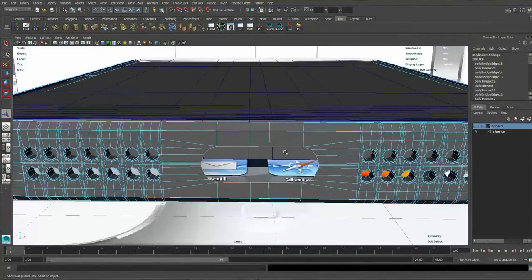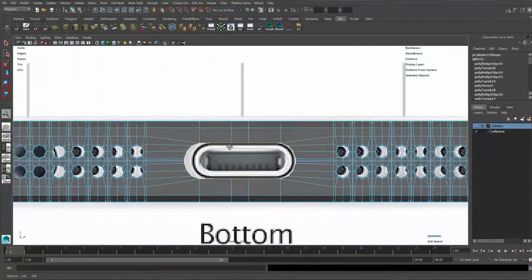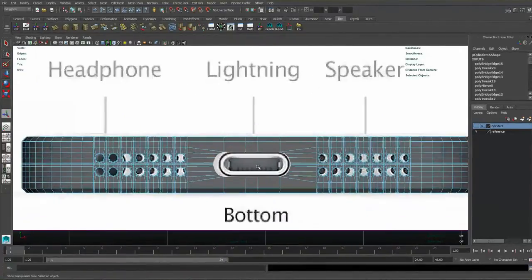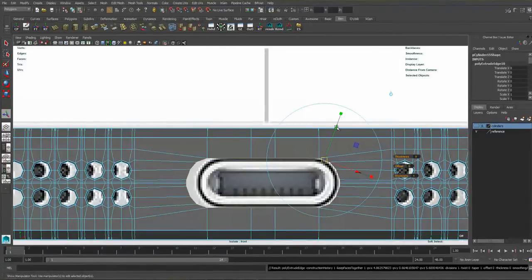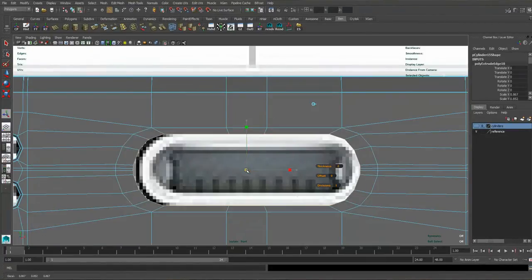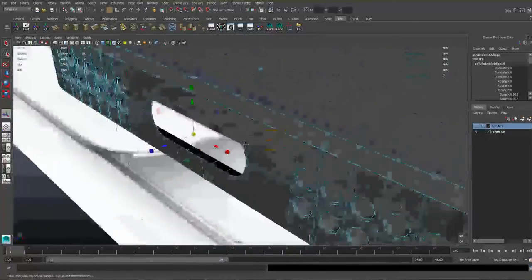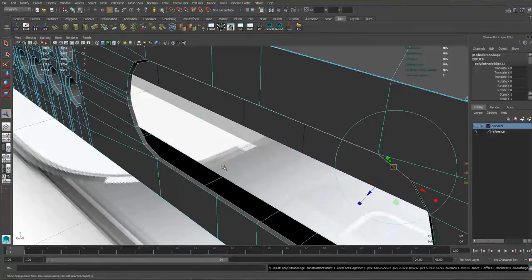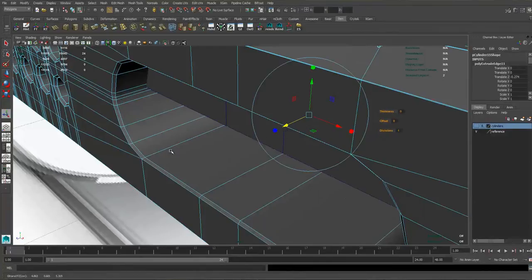Now we're ready to go ahead and put the little bevel in there, so we're going to need a reference image up for that. And again, it's slightly off, but I know since we've mirrored it, it is actually still in the middle of our phone, so I'm going to leave that. But I'm going to hit extrude anyway, and snap to grid button and resize like this, ever so slightly like that, that'll do. And then I'm going to go back to 3D view, and I'm going to move it in slightly like that, and then hit G to extrude again, click on the little power button-y thing, and then move it directly down into there.